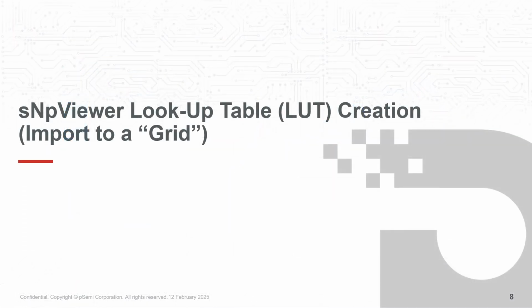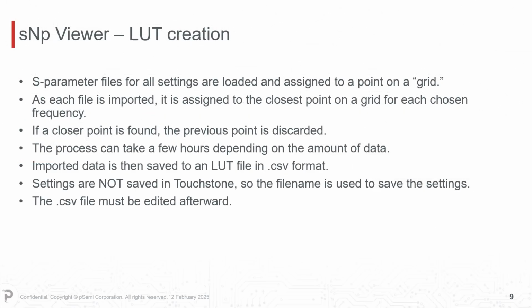One useful feature of the sNpViewer is being able to create lookup tables, which are used by one's host processor to optimize the phase or amplitude settings. This is the process for creating a lookup table.